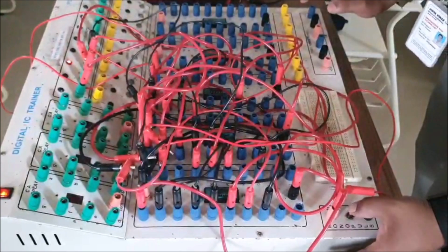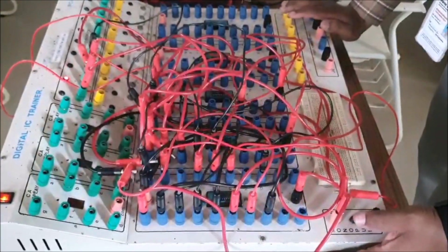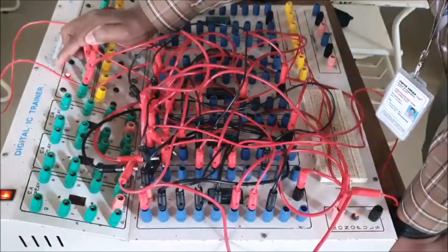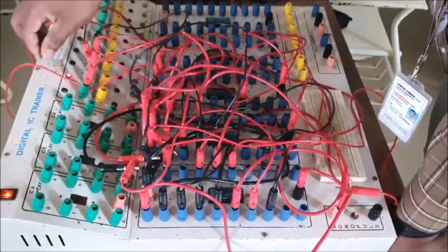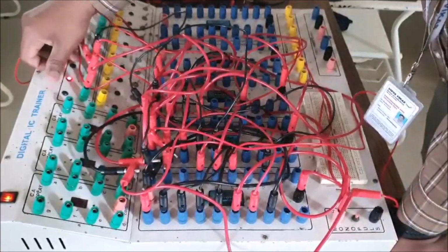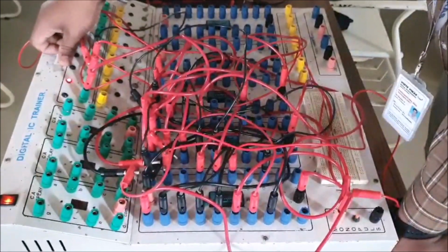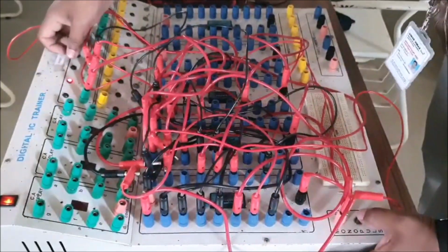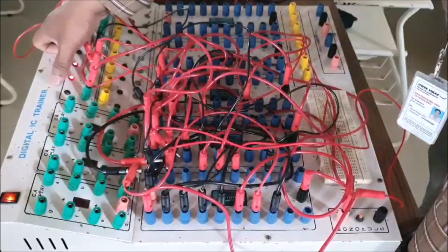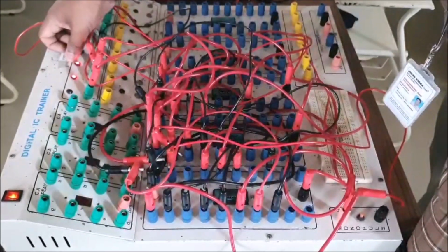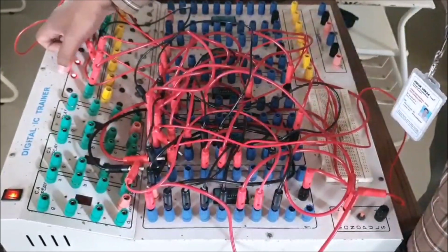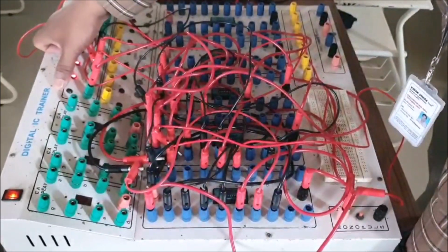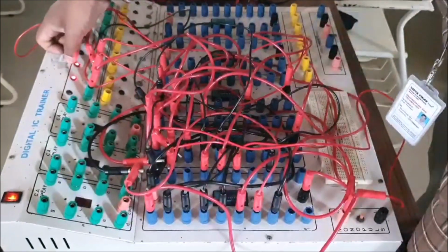Next, again I will press the monopulse clock. QB is activated, and the value of QB should be read as 1, and the binary representation is 010. For the decimal value 2, the binary representation is 010. Next, again I will press the monopulse clock. I get the output 011, which means that QA is activated, QB is activated, and QC is not activated, and the binary representation for the decimal value 3 is 011.